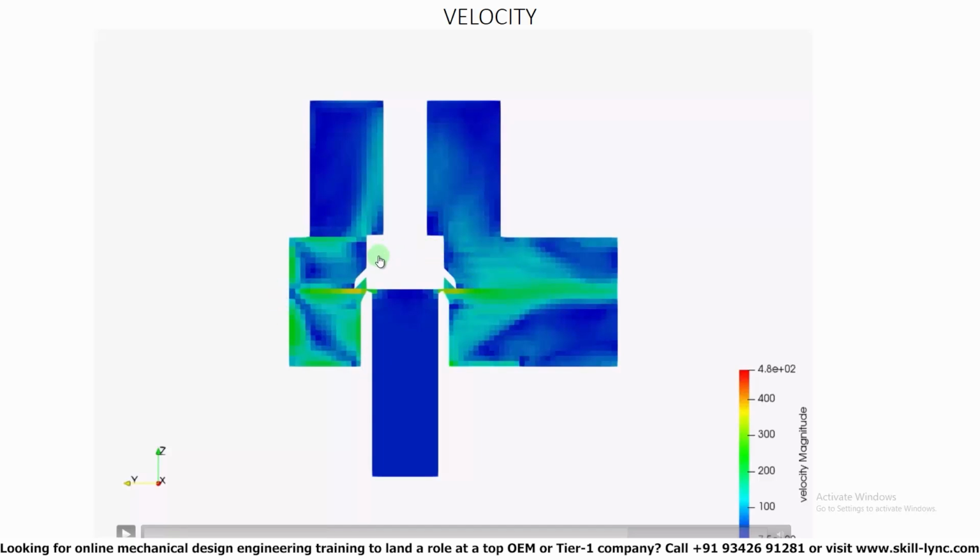Well, the short answer is, you can set up something called events within Converge Studio, and that way you can treat the pressure inlet and the rest of the pressure valve as separate regions, and you can control when those regions would be connected and when those regions would not be connected. The actual problem comes from the fact that two surfaces cannot intersect in pretty much any type of simulation tool, right? By default, it cannot unless you have some type of contact model in place.